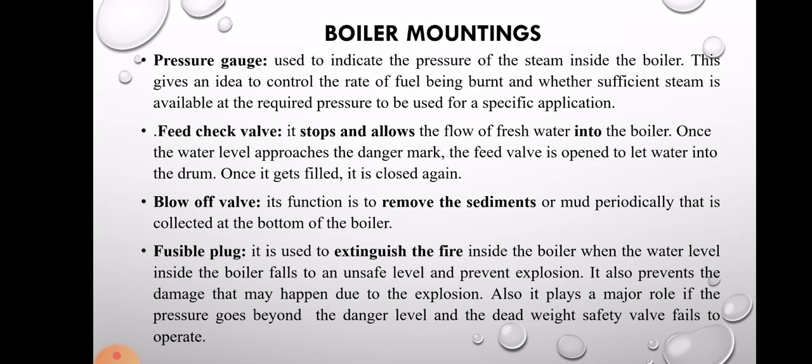Then we have a blow-off valve, or a blow-off cock as it is called in some cases. The function of this is to remove the sediments or mud which is collected periodically. Whatever care we take, there will be some inclusions or unwanted particles which will settle down, and they have to be removed from time to time. In case there is some calcification, that also has to be chipped off and removed in order to improve the efficiency of heat transfer. All this can be done by using this blow-off valve.